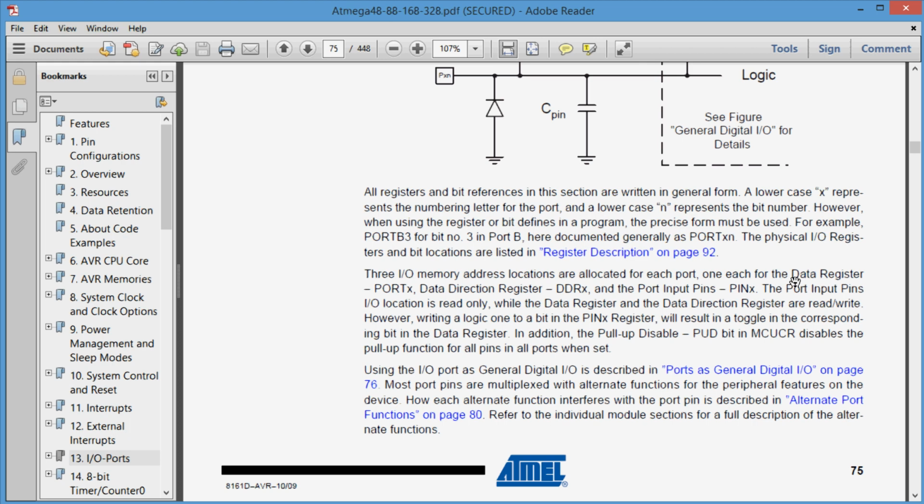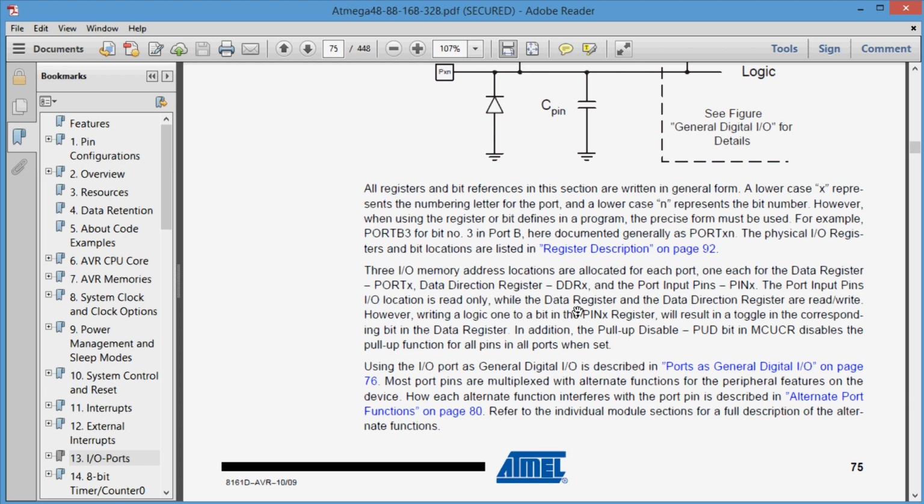Well, the data direction register, or DDR, as it shows here, if you write to that with the combination of 1s and 0s, that will set the I/O pins to be their inputs or outputs. So any pin that is written a 0, that makes it an input. Any pin that's written a 1 will make it an output. So in my case, for port D, because I want to make them all outputs, I wrote all 1s to those initially. Or I actually didn't do that in my software. I used the pinMode, but you could also do that to simplify your software.